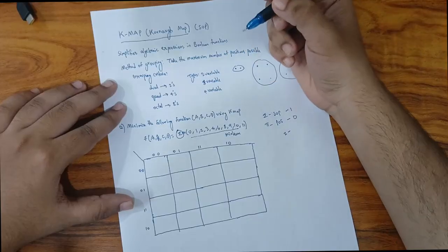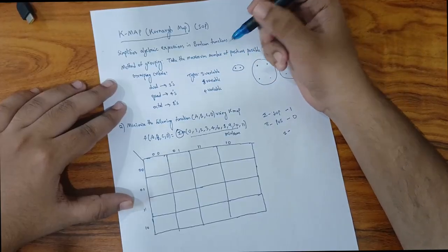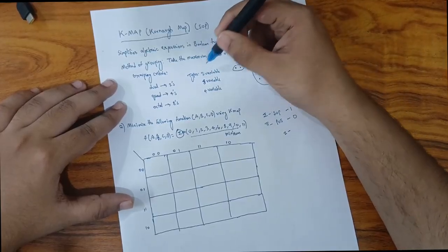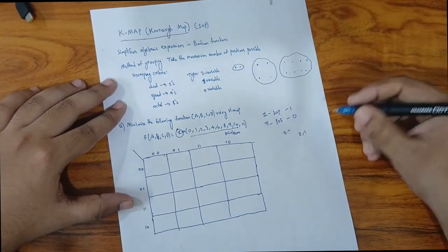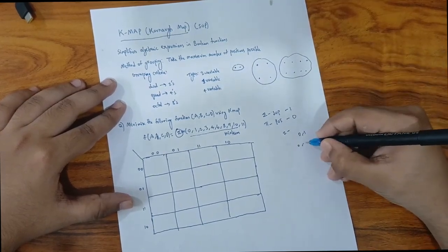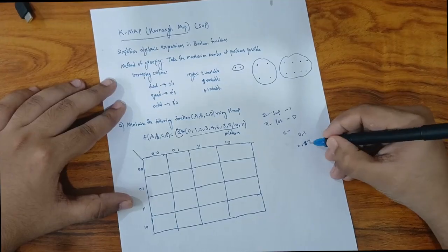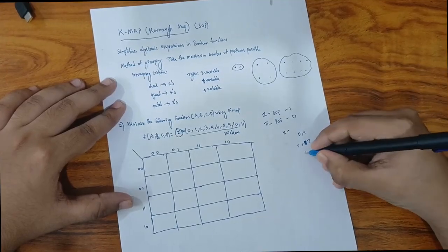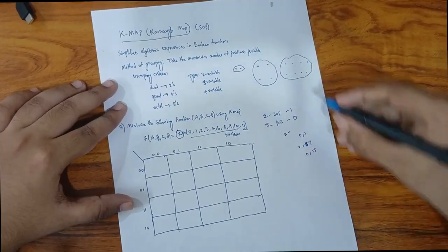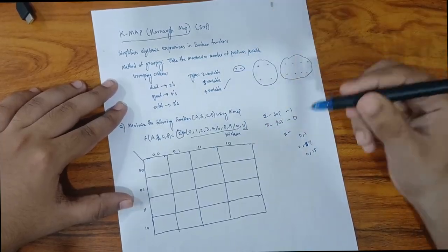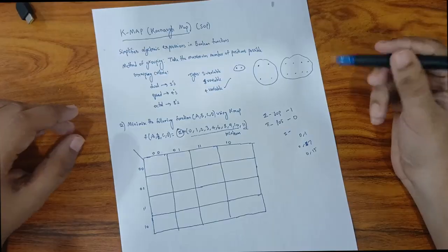There are different types of variable kmaps. There's a 2 variable type, which extends from 0 to 3, a 3 variable which extends from 0 to 7, and a 4 variable which extends from 0 to 15. The maximum term here is 11, which falls under the 4 variable kmap, so we need to make 16 cells for this.